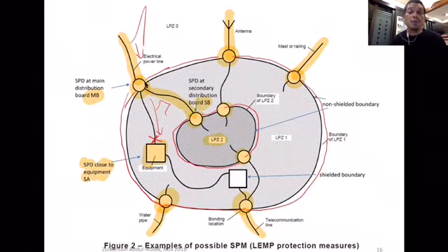You can see now, these are all using SPDs only, no shielding. If you want to do shielding, then you can shield the whole structure with one shield, but here you can see it's not a bold line. It's not a bold line, which means there's no shielding. The only shielding that we have is this equipment. It's a bold line here.